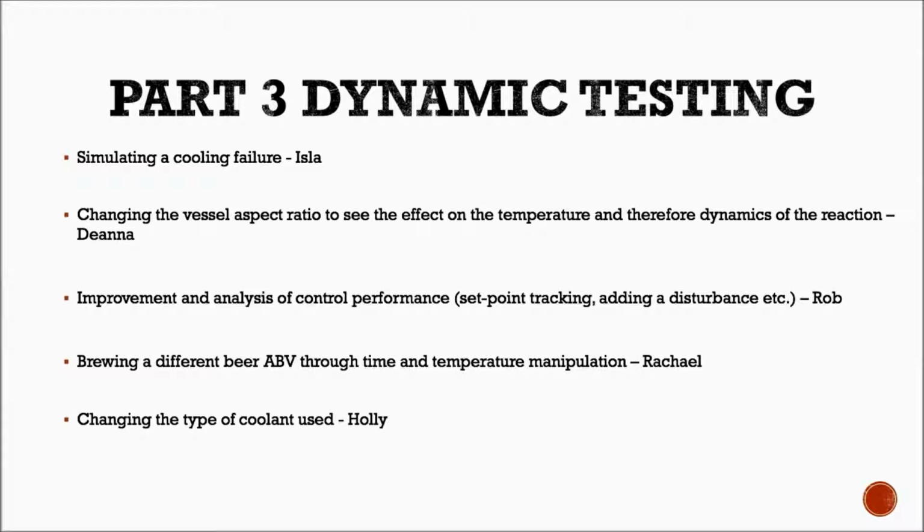It is very important to use the proper percentage of glycol to water in the system. Not enough glycol could lead to the system freezing up and possibly cause the chiller evaporator to rupture internally. Too much glycol will drastically reduce the chiller system's efficiency. My dynamic testing will involve varying the ratio of water to glycol in the coolant solution to see how the reaction rate is affected. The code will need to be modified so that it calculates the coolant mixture density and specific heat capacity depending on what ratio of water to glycol is inputted.